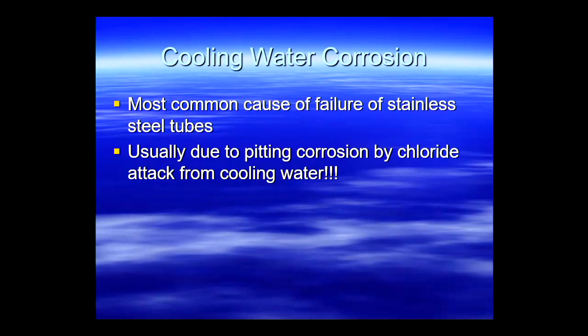It's always got a little bit of salt. In Melbourne, that is typically around 10 parts per million. In Sydney, it's about 100 parts per million. Most cities around the world control their chloride content to somewhere between 10 and 100 parts per million. After 100 parts per million, you can start to taste the saltiness. It tastes awful.